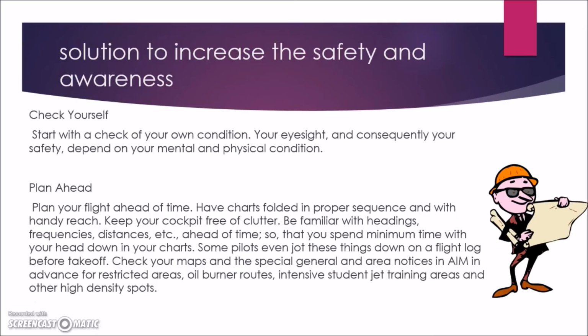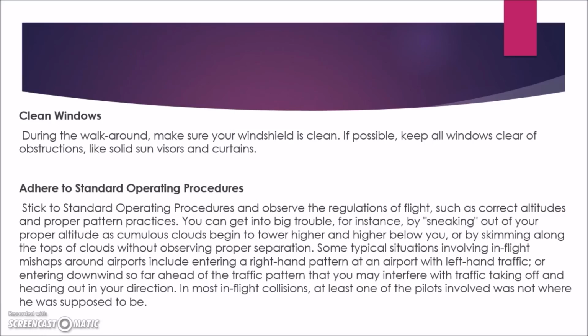Some pilots even jot these things down on a flight log before takeoff. Check your maps and the special general and area notices in advance for restricted areas, oil burner routes, intensive student jet training areas, and other high density spots.